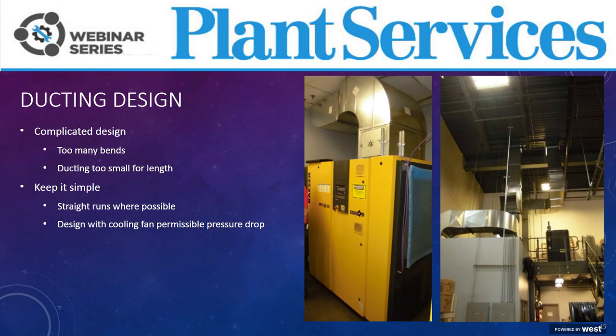As noted on that previous slide, internal fans only have so much pressure drop that they can handle. And when duct runs include too many bends and have long runs, that pressure drop is going to add up quickly, and that equates to overheating compressors. So longer straight runs are going to make a difference, as well as making the duct dimension as wide as necessary. The smaller the square footage, the higher the pressure drop, and the less reliable your system is going to be.